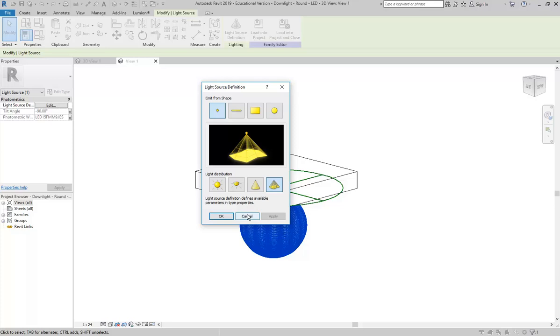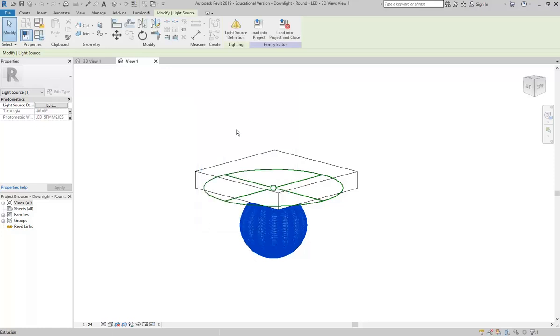So if you've got a scene with a couple of hundred lights, which is often what you'll need to get that nice distributed effect, the renders are going to go really slow. And also, it's probably not going to look as good as the other one I'm going to show you in a minute. So, it's good to know you've got these options, but that trick Rebecca just mentioned is pretty good. So, if you don't want to render with 3ds Max, you could have many small lights next to each other in a line to get the effect of a linear light.